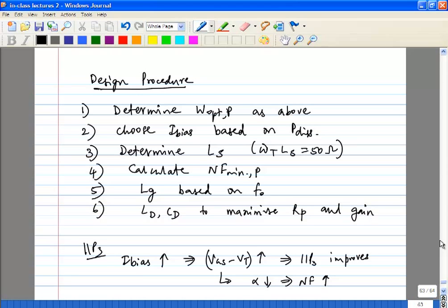There are cases where you are very close to the transmitter and may not require so much gain. So you'll have gain steps from maybe 20 dB all the way down to maybe 5 dB or 3 dB. Obviously, when you're closer, your signal is larger, and you don't need such a good noise figure from your receiver. So once you detect such a large signal, you would automatically set your LNA to a low gain state.